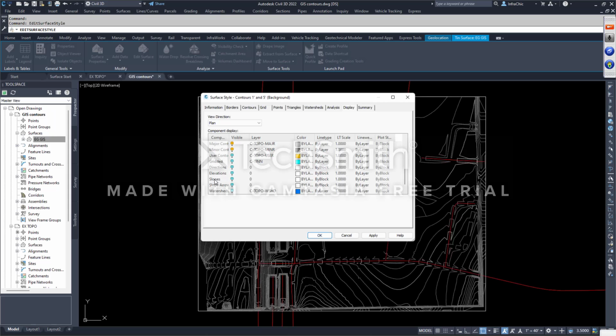Slopes, and this would be slopes in massive swath patterns, so not arrows, but like a solid hatching of a certain color, and that color indicates the slope is 2%, 3%, or 4% in this area. Slope arrows, again arrows, but colored, related to 1%, 2%, 5%, 10% in that area, showing the direction of flow. And watersheds.